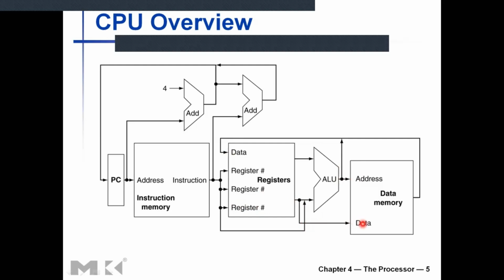If you are reading from the memory address, you give the address, you read the data, and that data will come into the register file, and you write that data into the register file. Right? So that covers most of the cases that we have in the set of instructions. R-type instructions, I-type instructions like loads and branches, and everything is covered under what we have in this diagram. Do you have any questions on this?